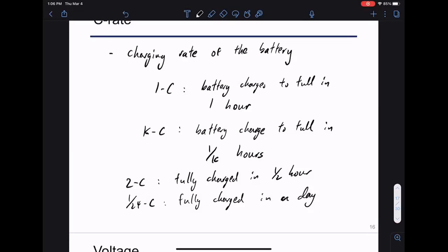That is one important factor in how fast you can charge a battery. Another consideration is safety. Try charging a battery too fast and something catches on fire. So the C rate is determined by the degradation characteristic and the safety characteristic.